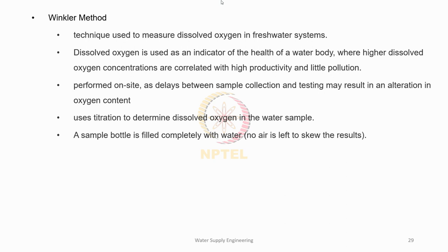So a sample bottle is filled completely with water, that is, from the site we'll take the sample in a sampling bottle. As you know, whenever we are using a sampling bottle, it should be rinsed with the same liquid that we are going to test.